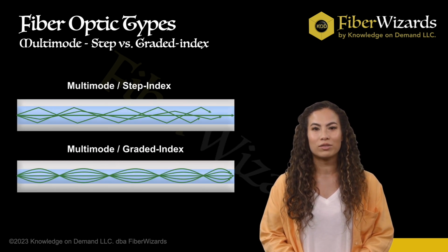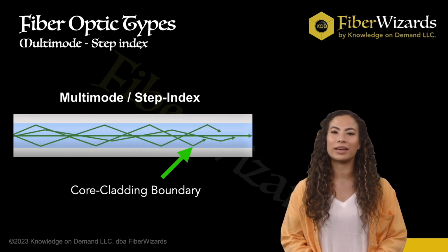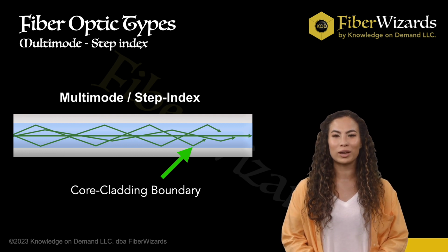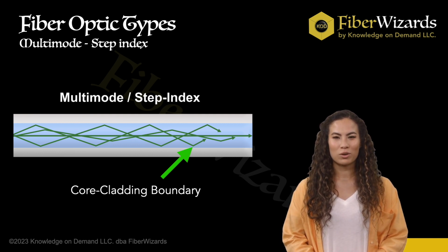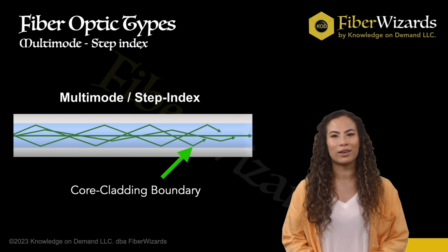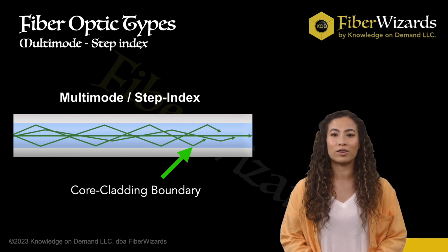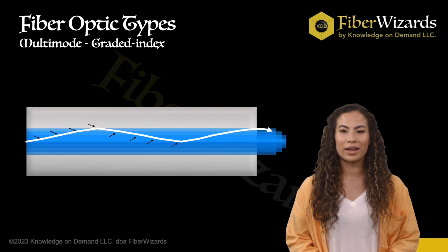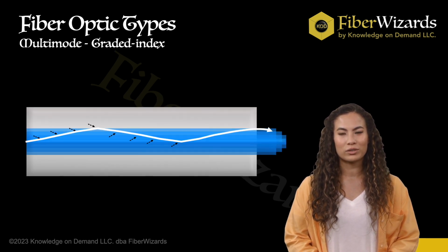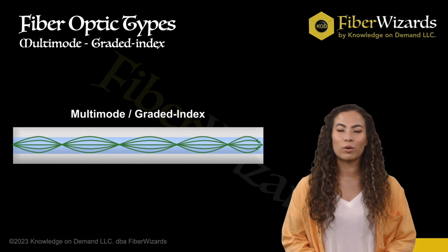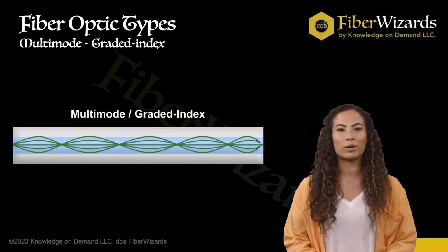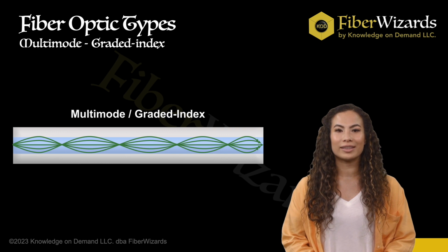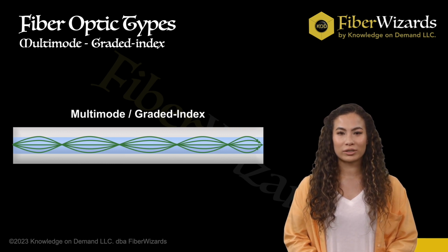Multimode fibers are made with different designs known as step index and graded index fibers. Step index multimode fibers are built with a slight refractive index differentiation between the core and the cladding to make light modes bounce off the core-to-cladding boundary as these travel through the fiber. On the other hand, the cores in graded index fibers are built in layers, increasing refractive indices gradually from the core's center out to the edges. This technique of layered cores in graded index fibers forces light modes to follow more similar trajectories as these travel through the fibers, to reduce modal dispersion.